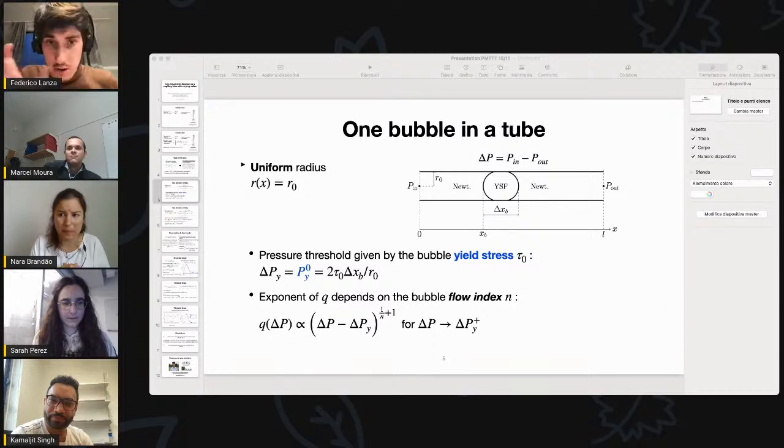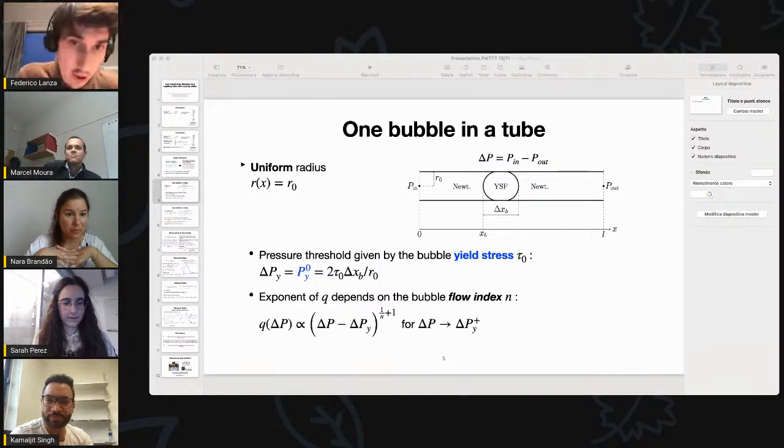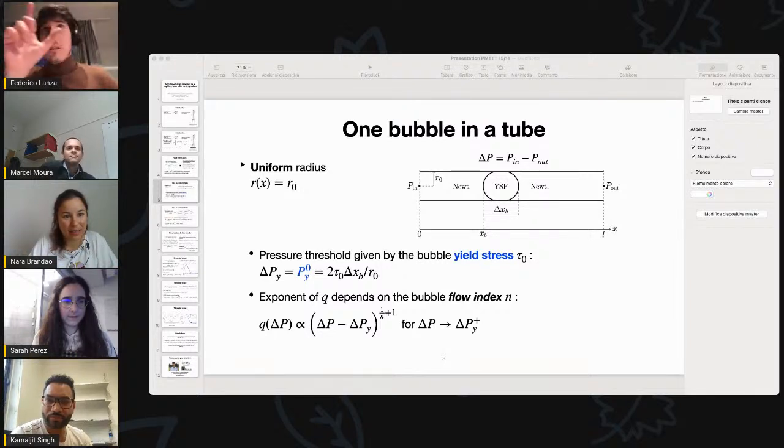So we compute the surface tension contribution at the surface of the bubbles. For a constant radius, it comes out that this contribution is 0, but this is a fortunate case, while for a non-uniform radius it's not 0. For the other drops, the viscous contribution is the fundamental one. So in this way, we take into account both contributions. Okay, great. So it's implemented in the equation.